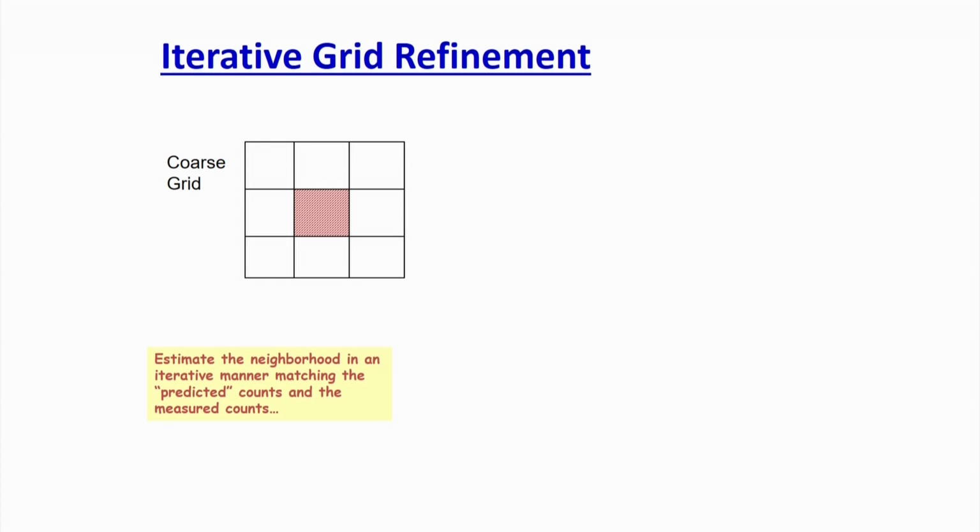So what we do? We do the experiments, in which the particle is moving freely. The Monte Carlo program is ready, and it can calculate the count at any location inside the bed. Suppose this is my column, and in the experiment the tracer particle is moving freely. This is the tracer path, it started here and is moving freely. I have to reconstruct the position of the particle. I have already tuned my Monte Carlo program, which for a fixed location of the particle can give me the count on all the detectors. The detectors are placed here.